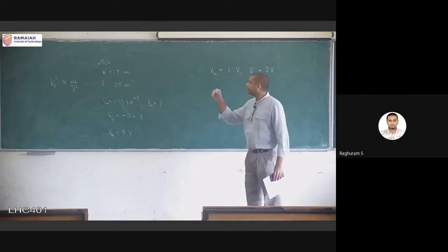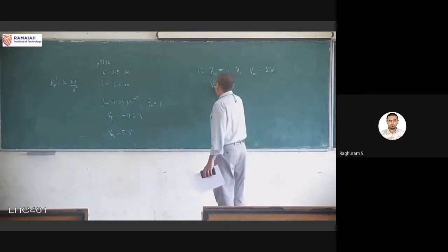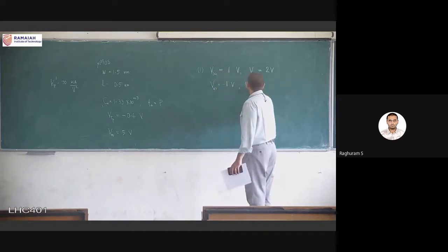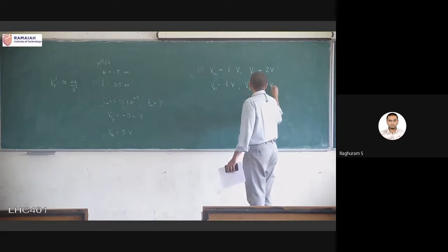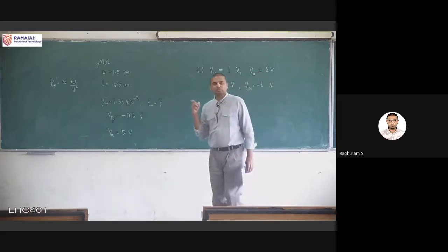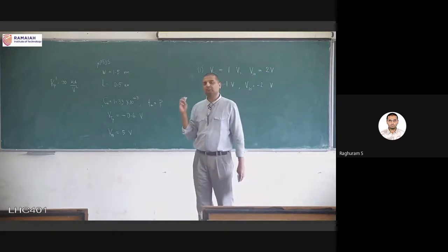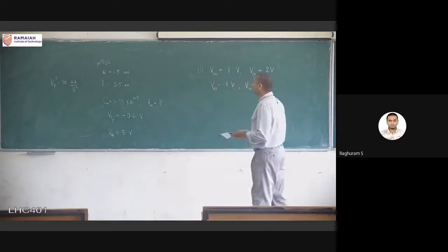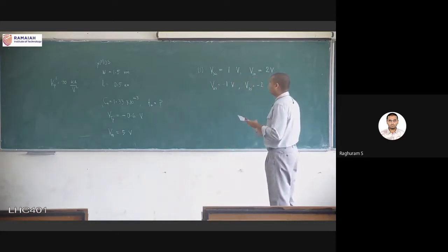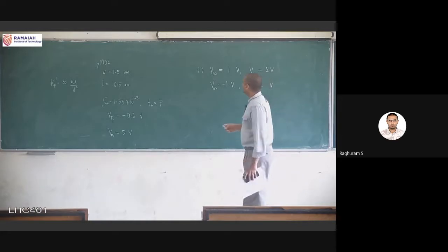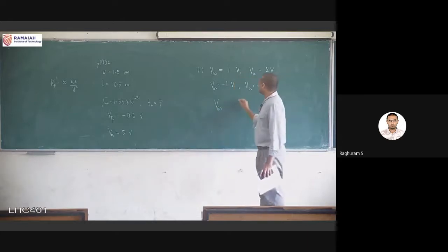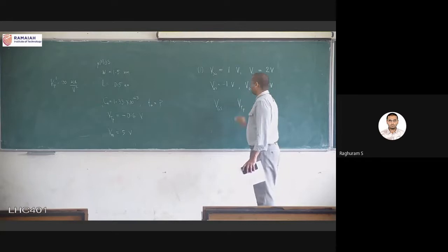So to go from one to another, first I have to get these variables. We cannot use those variables at all, the first set that is given. So get it in terms of the variables that we use, and then we can go for the calculations. So they want the current, obviously. First VGS is minus 1 volt, VGS minus 1 compared with VT, which is greater.